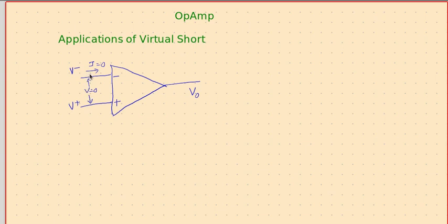And if you look at the connectivity between the two inputs, then in each direction the emitter base junction of one of the two transistors gets reverse biased. In one direction, from negative to positive, the Q2 base emitter junction is reverse biased. In the positive to negative direction, the base emitter junction of Q1 gets reverse biased. So whatever be the case, it is sure that no current will flow between the two input terminals.